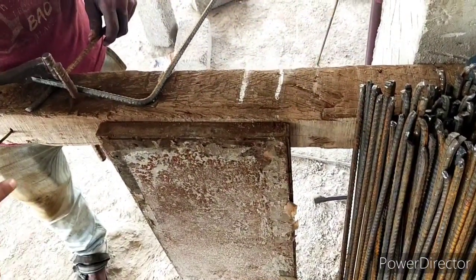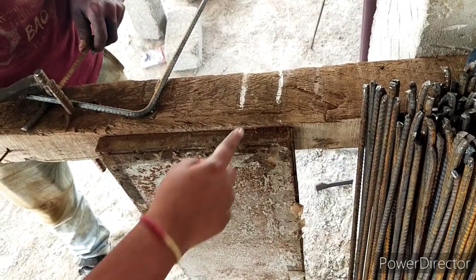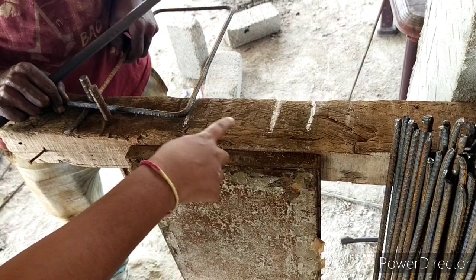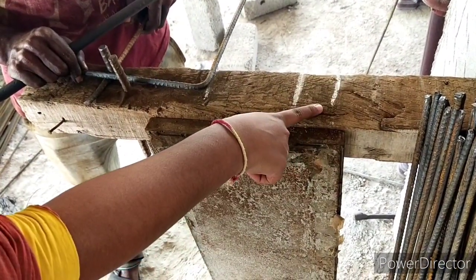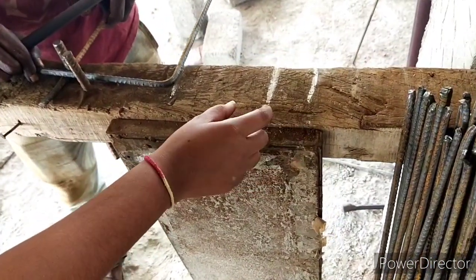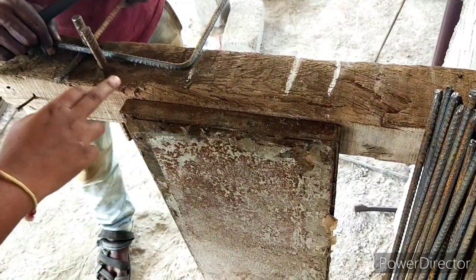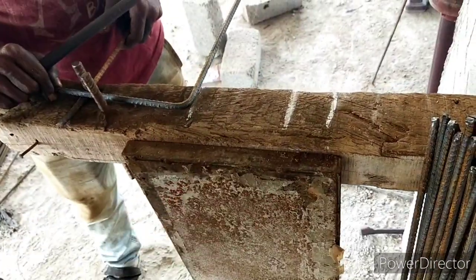This is the stirrup making process from the side. First, before making the stirrup, we mark these labels. This line is the length of the stirrup. This is the breadth of the stirrup. This mark is the bend of the stirrup. Here our bend is 80 mm, the length of the stirrup is 620 mm, whereas the breadth of the stirrup is 220 mm. Now we will see how it is made.